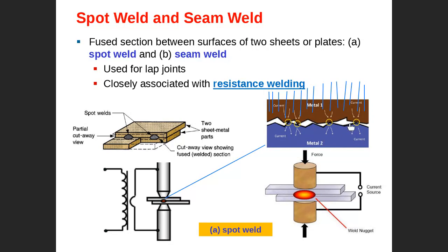What will happen? Current cannot pass from up to down except through a few points, which are the contact points between surface 1 and surface 2. You see only a few contact points here. Then you get a traffic jam. All the current has to pass through only a few points. This is what we call resistance. This area becomes very crowded with the current, and then you get a loss in energy.